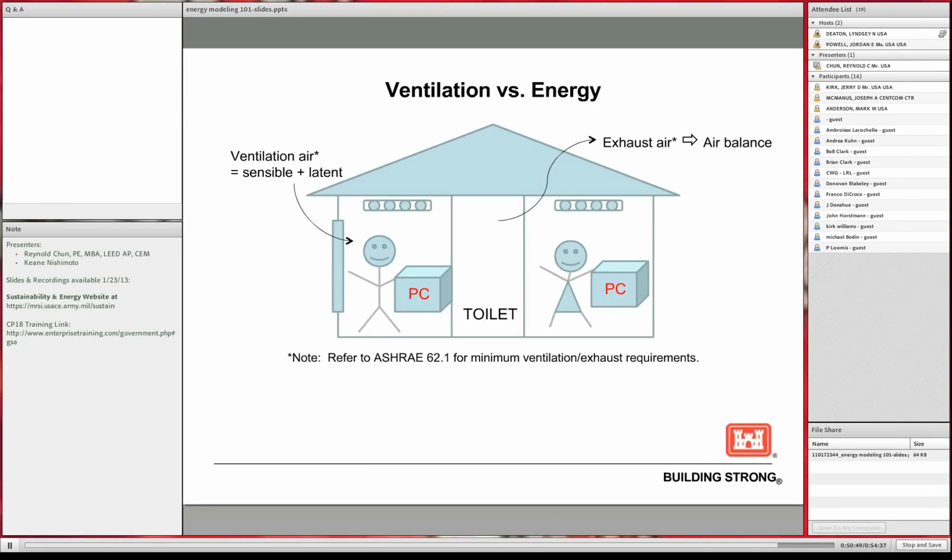In terms of people opening and closing doors, we just have to assume that the doors are closed. You can account for a certain infiltration rate. In Carrier HAP, there's an infiltration rate you could add either by CFM or by CFM per square foot. So one is an absolute airflow, not relative airflow based on square footage of the building.